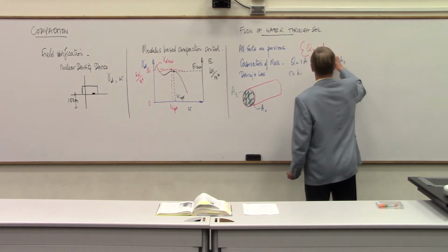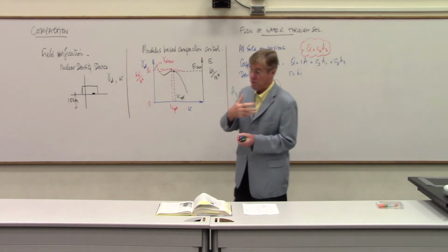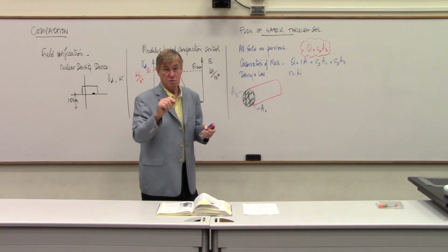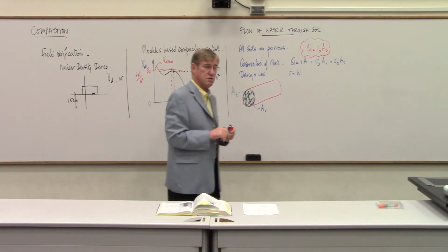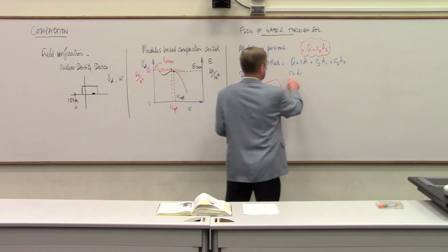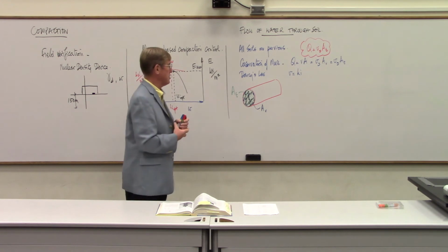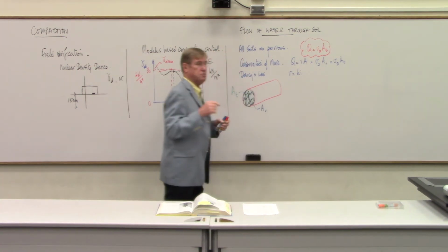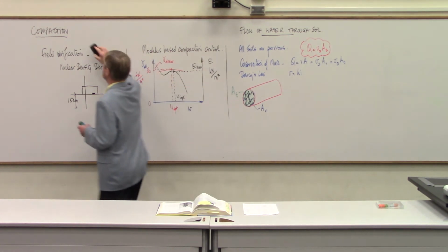All right? First equation. And I can tell you, if in the midterm you get a problem on seepage, the first reaction is to write Q equals VA, and then the second one, V equals Ki. And we're going to discuss V equals Ki next. Again, this V right there will be V discharge, because that's the one we're going to be using from this point on. But before I can talk about Darcy's law in more detail, I need to go through a few definitions. So let me erase this.